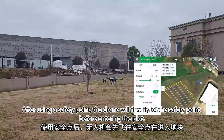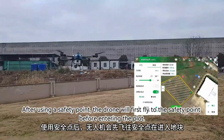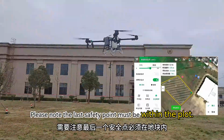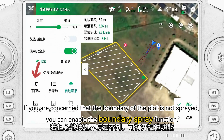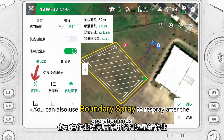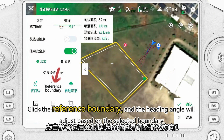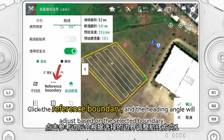After using a safety point, the drone will first fly to the safety point before entering the plot. Please note the last safety point must be within the plot. If you are concerned that the boundary of the plot is not sprayed, you can enable the edge sweeping function. You can also use boundary spray to respray after the operation ends. Click the reference boundary, and the heading angle will adjust based on the selected boundary.